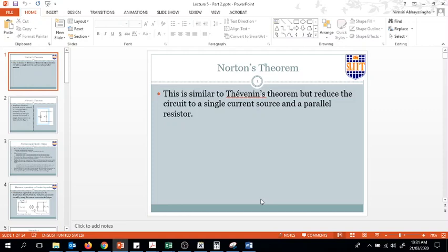And the Thevenin's theorem helped us to convert the circuit, excluding the resistor that we are considering, into a voltage source in series with the resistor, so that we could make any changes to the resistor and check the behavior of the circuit, or basically the voltage or the current of the resistor could be observed by making any changes to the resistor value.